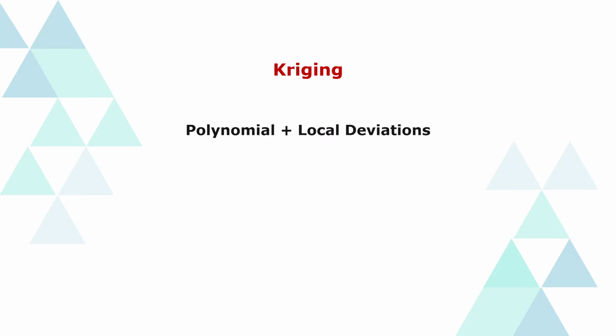Kriging is an accurate multidimensional interpolation method that combines a polynomial model similar to the standard response surface plus local deviations. In other words, in the global model, we fit a simple polynomial across the design points, which does not necessarily intersect all the design points. The kriging method applies the local corrections based on local deviations to the global model to interpolate the design points.